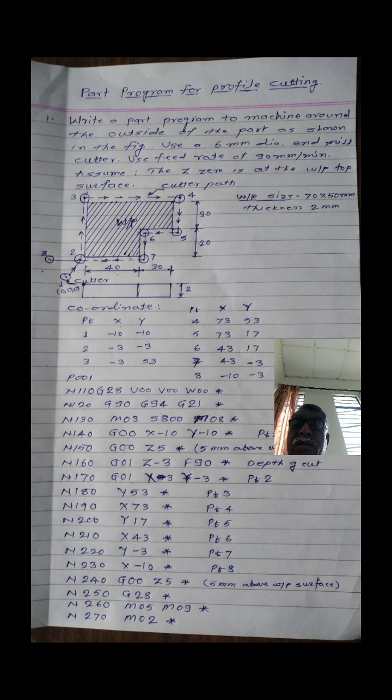Then find out the coordinates of point 6. Here the y coordinate remains same. You have to find out the x coordinate from the workpiece 0.